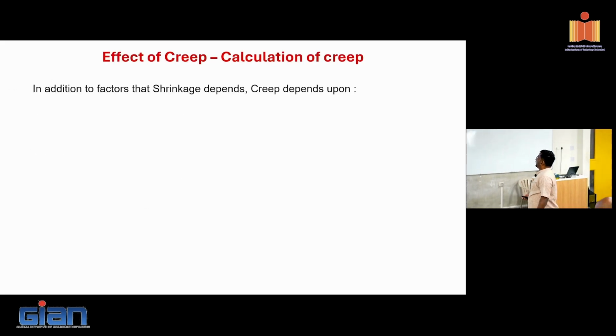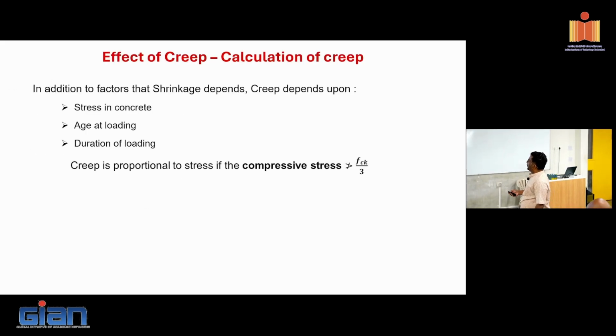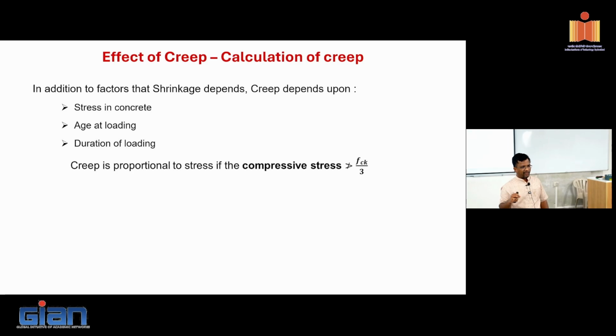Right, anyway, in addition to that, creep depends upon stress in concrete. The higher the stress, when do you have micro cracks in the system? Let's say I load the concrete in compression. When do you develop micro cracks or interfacial cracks? Typically, when the stresses are more than 40% of your compressive strength, you develop all these cracks. So the higher the stress, the more micro cracks in the system, and then there is more passage for the water to escape out of the system.